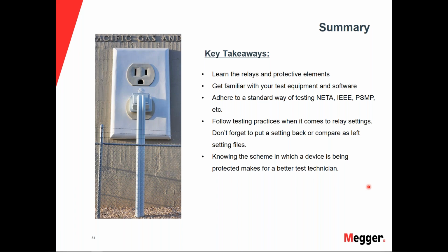Know the scheme in which your protection, what you're testing. If you don't really understand what you're testing, then maybe it's very difficult for you to know the right and wrong from the relay test reports. If you're just going out there just running a few tests and just handing in the document, and somebody else is overlooking you because you didn't really understand what you were testing, then you have to go back out there.